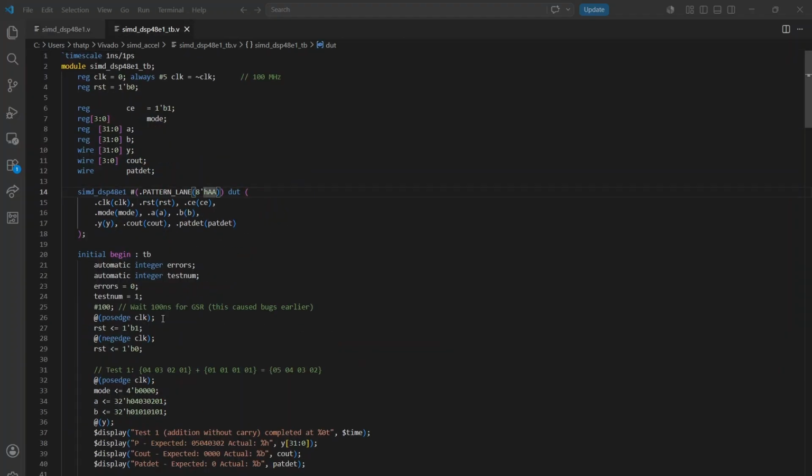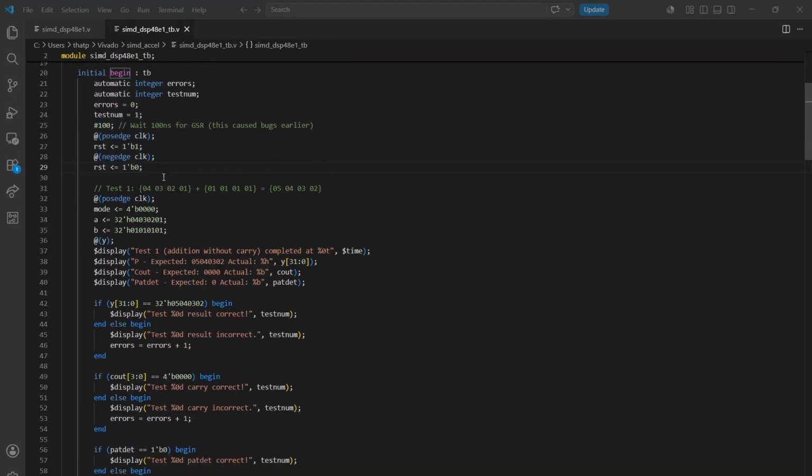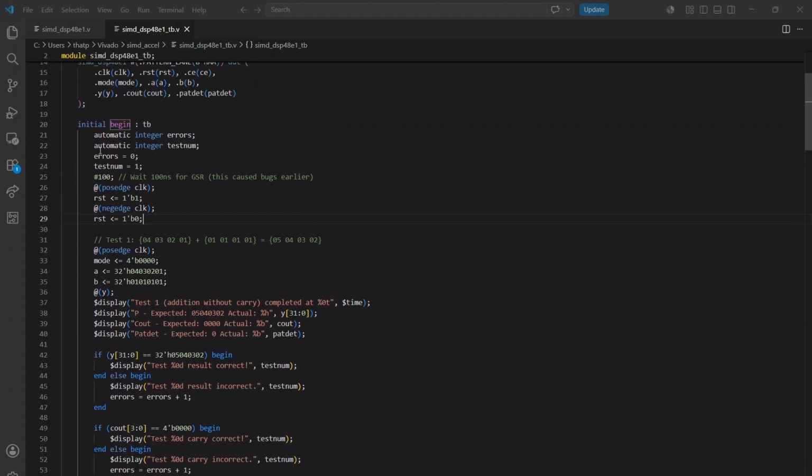And then for my test bench, it's a very simple monolithic test bench. I was going to do something more complex using a driver, monitor, and scoreboard, but from what I could find, Verilog doesn't actually support that kind of functionality. At least I know for a fact it doesn't support mailboxes, and that's the only way I've implemented that stuff in the past without using UVM, so it seemed like a monolithic approach like this would be sufficient for a pretty simple design anyway.